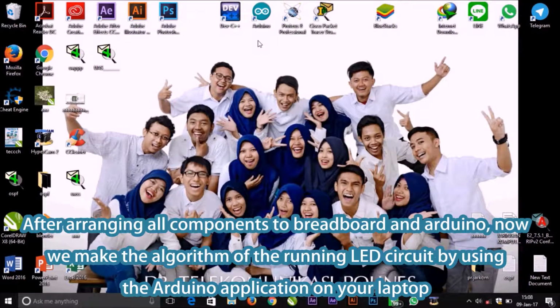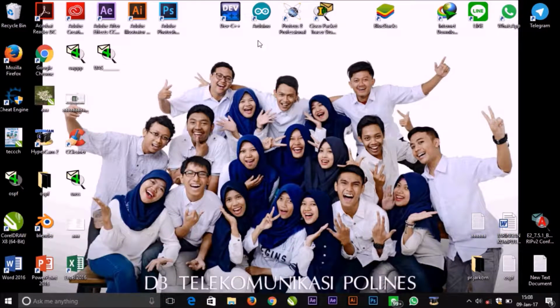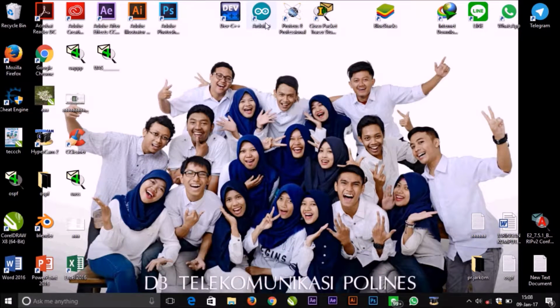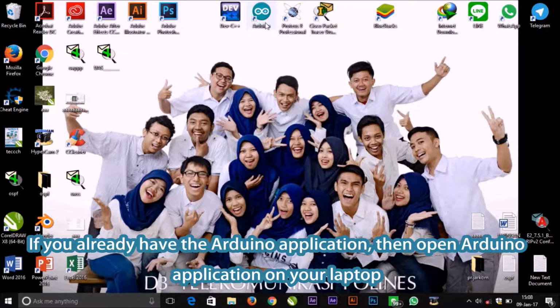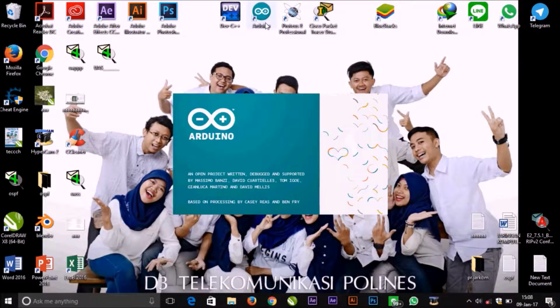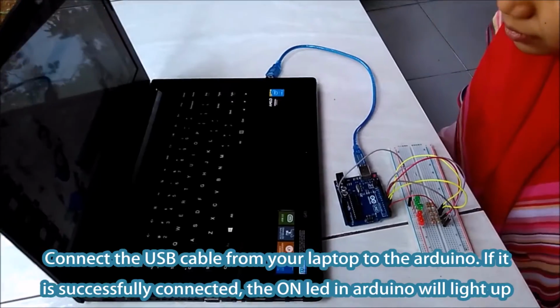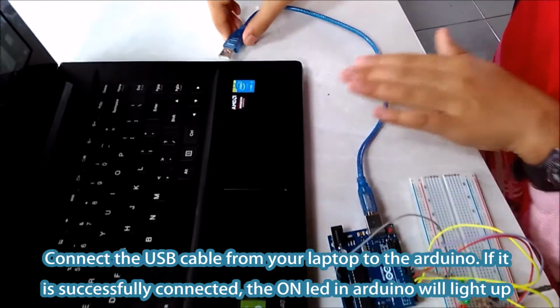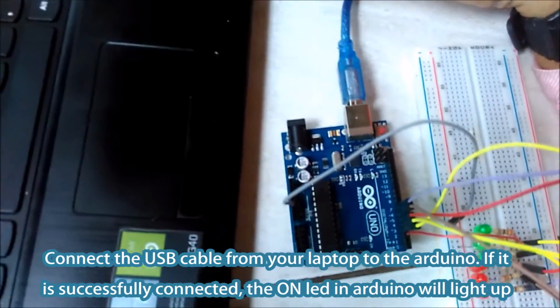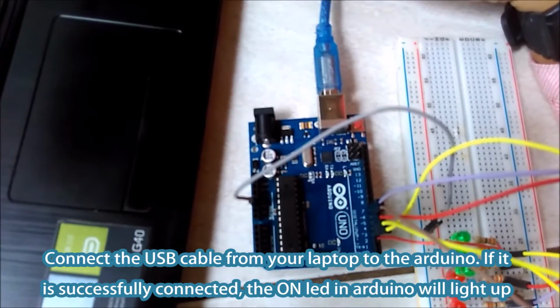After arranging all components to the breadboard and Arduino, now we make the algorithm of the running LED circuit by using the Arduino application on your laptop. First, prepare the application by installing it. If you already have the Arduino application, then open it on your laptop. Connect the USB cable from your laptop to the Arduino. If it is successfully connected, the on LED in Arduino will light up.